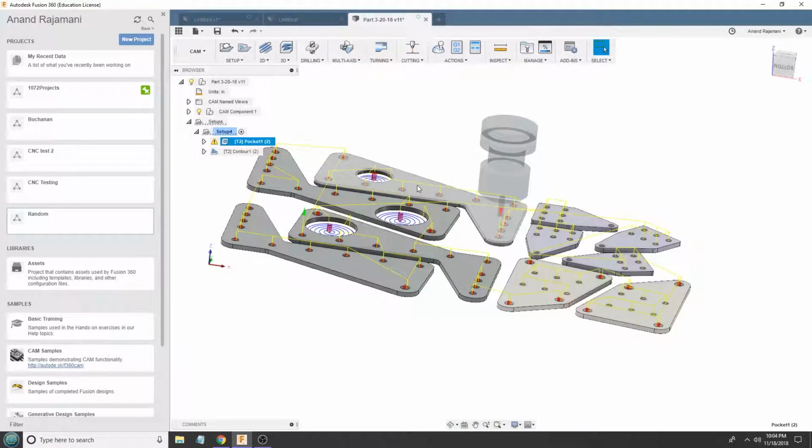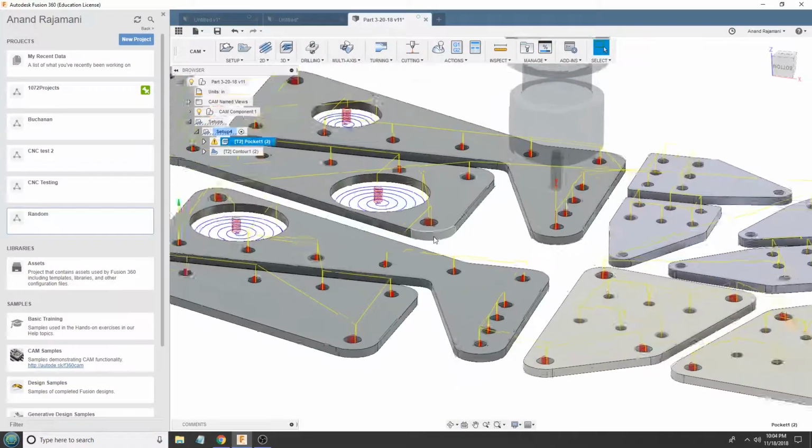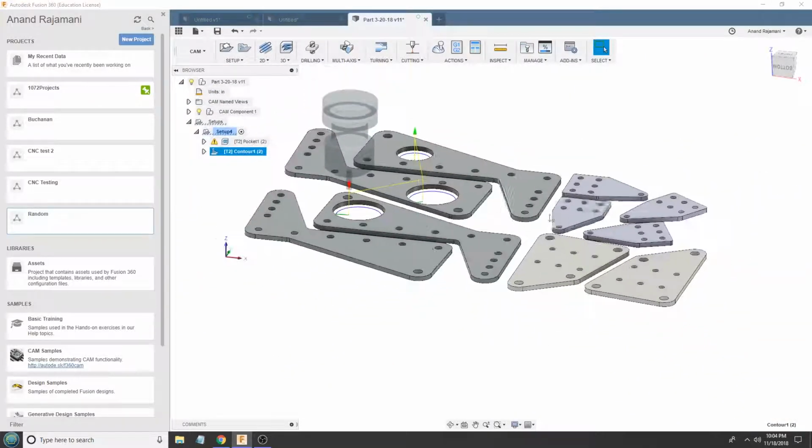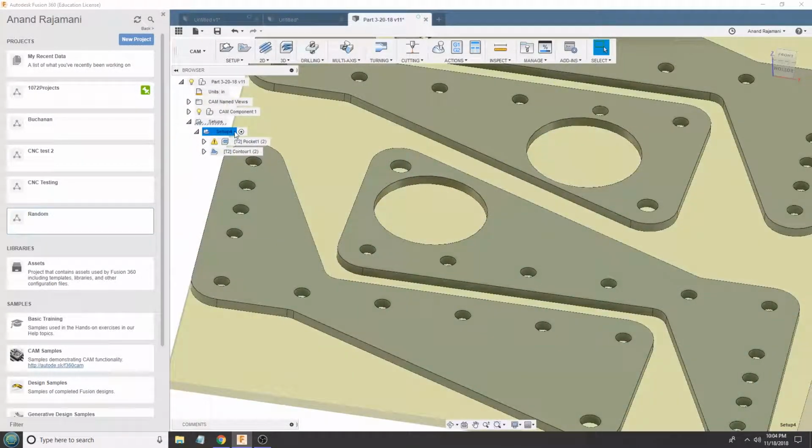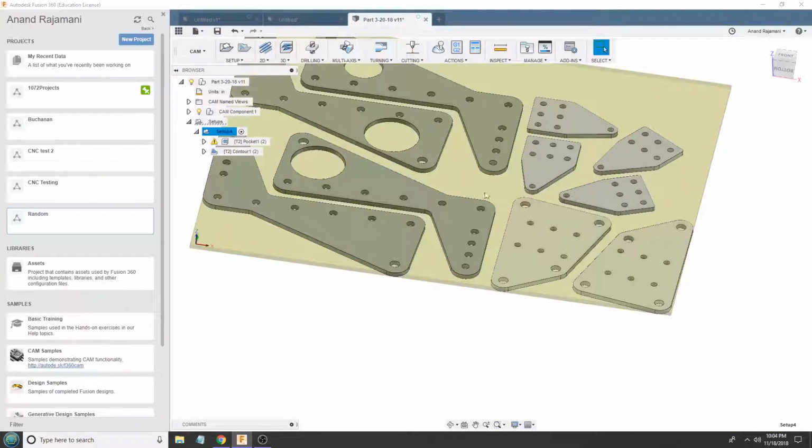And for a router, most of what you're doing already is slotting. And in this case, because it's all 1/8" material, I'm definitely slotting all of this. And the contour is just going to go in there and finish all these up. Real straightforward. Takes just however long it takes for you to click on all the parts in your program. And you can even do it faster than that if you find a way to optimize the way you're selecting stuff, which I like a lot.